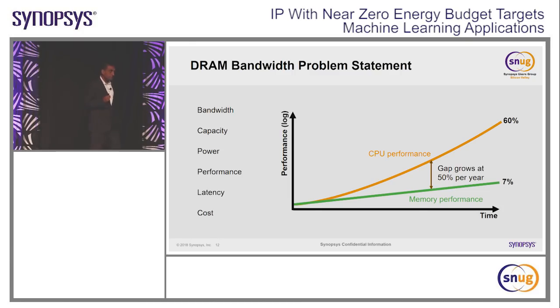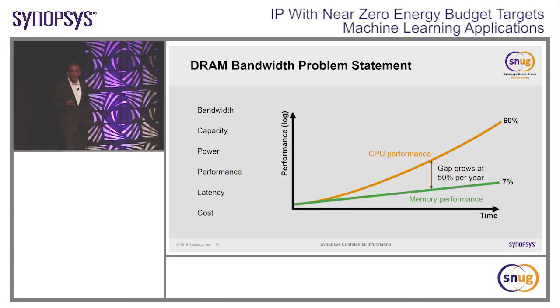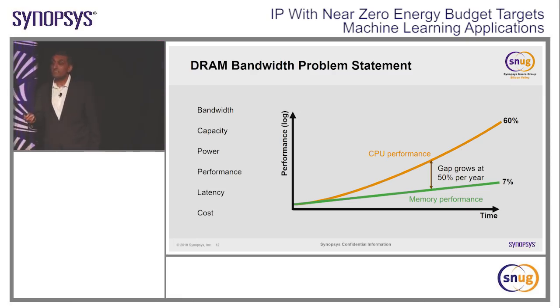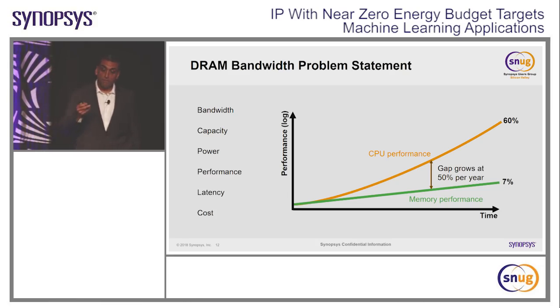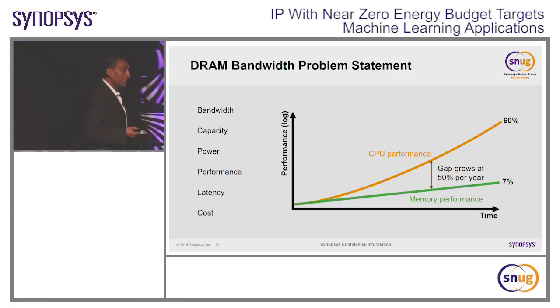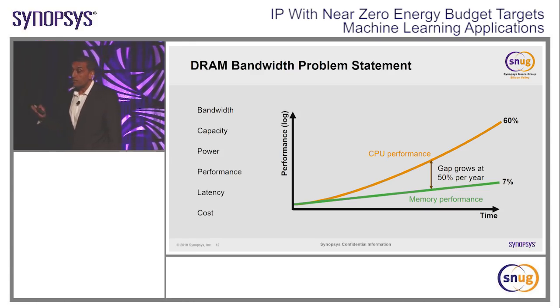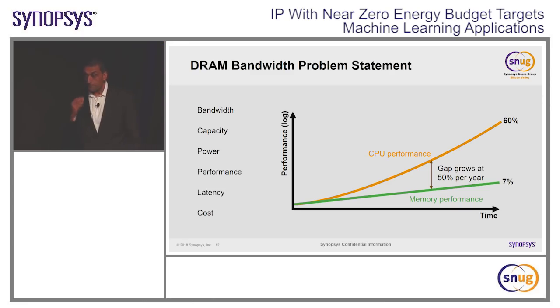Generally, these chips communicate to an off-chip memory, right, to a DRAM. What's happening is that these DRAMs are not keeping pace with the scaling that was defined by Moore's law. So you can see that if you compare the orange line to the green line. The CPU performance, the SoCs, have done a great job in scaling with Moore's law, but the DRAMs are somehow struggling in order to support that scaling law. The memory bandwidths for some of these applications are outpacing the capabilities of DDR. These applications include high-performance computing, network applications.